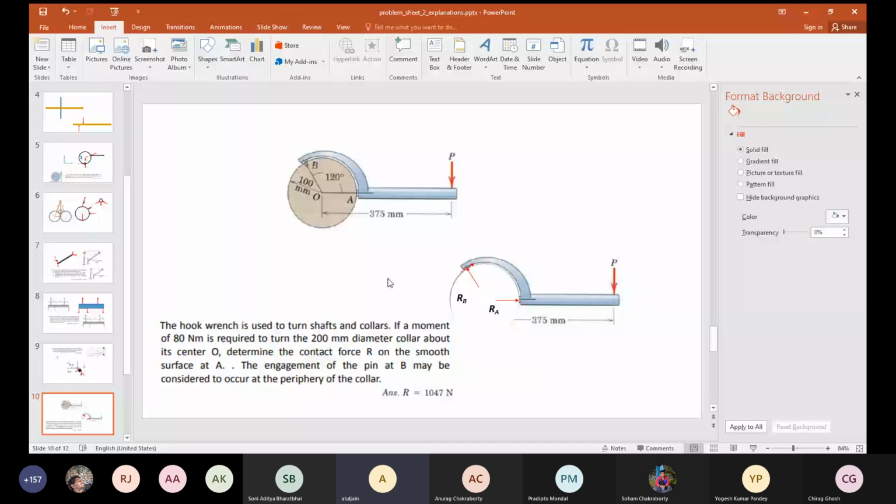Because I think what you are saying is, since we are making a hole, if we imagine this small slot, if it wants to move down, it cannot move. If it wants to move sideways also, it cannot move, right? Yes, sir. So there should have been two reaction forces. Yes, sir. There will be three forces and three equations: X equilibrium, Y equilibrium, and moment equilibrium. And then you'll get the answer.